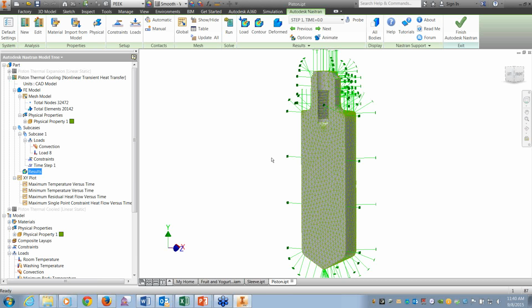I can add to the material property. I add my constraints and my loads. Similar to what I've been used to in the past with Inventor Professional, with a lot more capability, both on the constraints with the symmetry availability, as well as the loads with thermal loads, transient loads, and also the availability of other styles of contacts. From there, work my way across left to right, mesh the design, and go ahead and do the run.